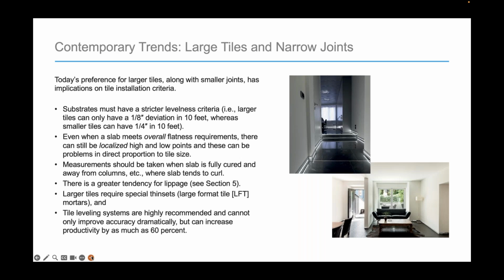Even when a slab meets overall flatness requirements, there can still be localized high and low points, and these can be problems in direct proportion to tile size. Measurements should be taken when the slab is fully cured and away from columns, etc., where slabs tend to curl. There is a greater tendency for lippage. Larger tiles require special thin sets, like an LFT.